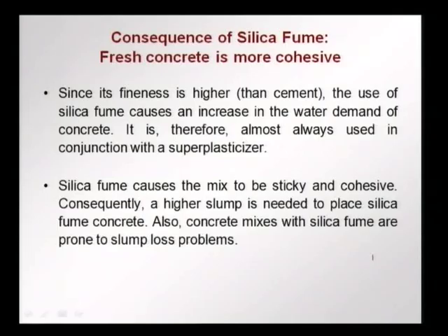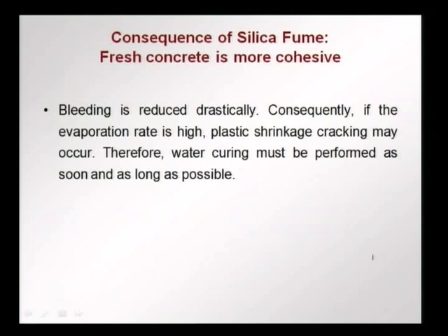Also, we should understand that silica fume concretes are prone to slump loss. So, we have to be careful in terms of the superplasticizer dosage and the time needed for transportation of such concretes. Bleeding is also reduced drastically. Bleeding is the excess water that floats to the surface and can be under the aggregates and rebars as compaction occurs. We will discuss it a little bit more in detail in the subsequent lecture.